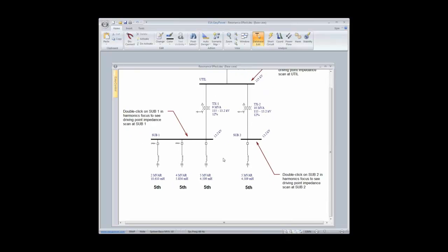And I will just have to admit here, on the inside of EasyPower, this filter wasn't necessarily put in here for designing. It was predominantly put in here just to simulate it. But if you're doing harmonic filter design, you actually want to see the actual voltage and conditions on this capacitor itself. And in that case, you may want to break it out.